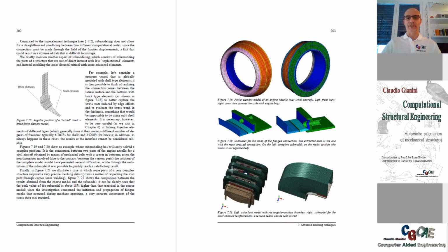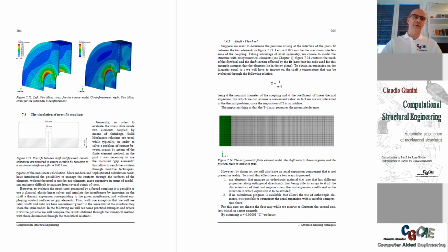And here as well, this is an autoclave with a rectangular shape, so the chamber is rectangular, not the best for resisting pressure, and for this reason we have stiffeners outside and welded connections. Here it was necessary to have a very fine mesh to adequately catch the stress distribution, because some cracks were propagating in some of these reinforcing parts.